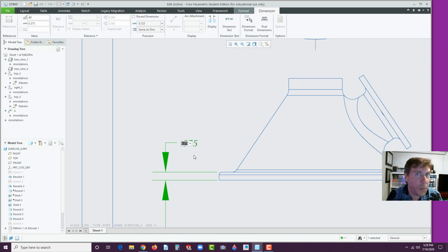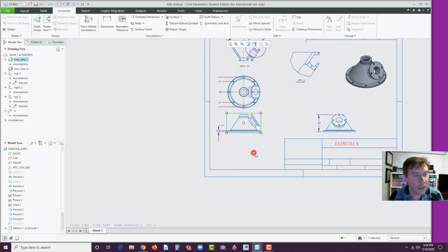And that was so if he ever got a call from a customer, and let's say I was gone, he could go in just to the drawing, find the dimension, because changes always occur. They say, hey, you need to thicken that. Could you make that a 1/2 inch? He could go in, type it in, update it. It'll update the drawing. It'll update the models. So very powerful functionality, but you have to be careful. You don't want everyone going in there having access to change those. And there's options for the ability to adjust that so that doesn't happen with PLM vaulting and such.